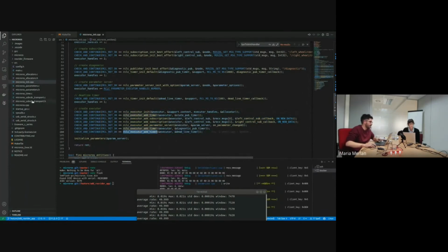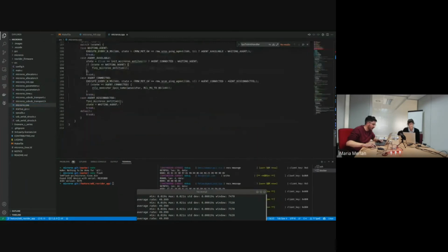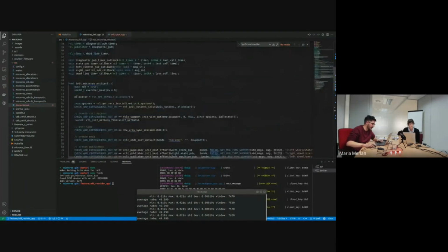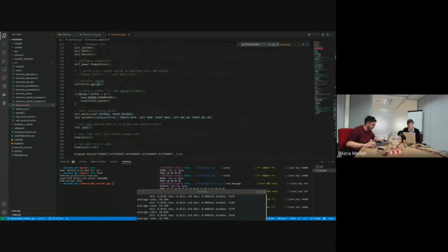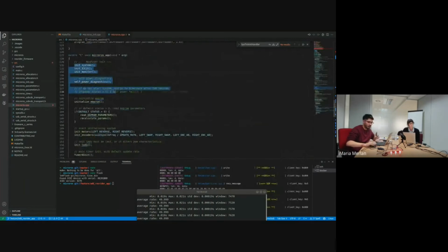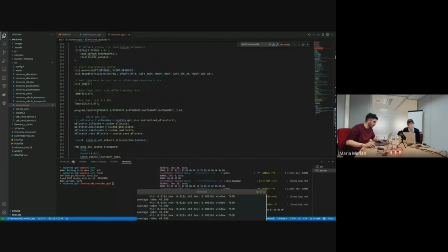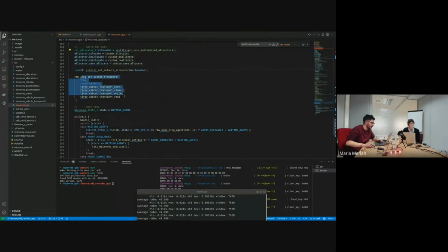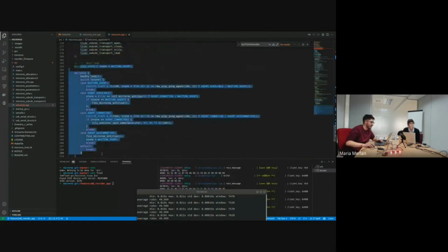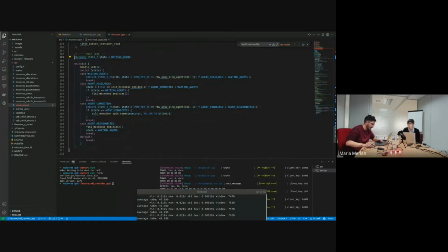This timer is important because if we go to the application, this was the micro-ROS creation functionality, but here we have the main functionality. We can see that we have a lot of functionality that the creator of the board has provided to us, for initializing all the systems and connecting to all the devices that are on board, for example, using I2C or initializing the EEPROM, all the things that the board needs to do. But here we have our micro-ROS application with its allocators and with its custom transport and with the same state machine that I have shown to you in the other demo.